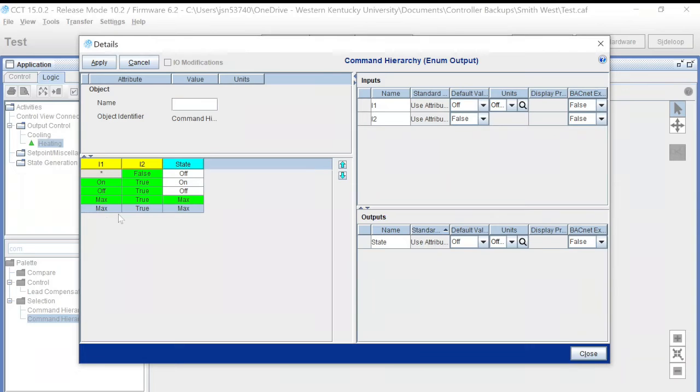And guys, in practice, your freeze protection should be up high on the priority. So we can actually move that up just like this. Okay? Even if my system enable is false, if that hits max, then I want it to turn on and protect that system.